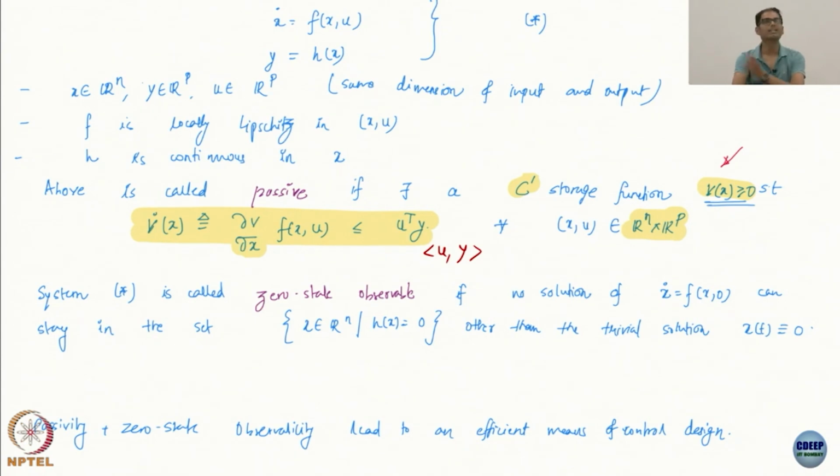So basically the way all these definitions are stated, observability, controllability, it says that you can reconstruct the state from the observations. This is the thing, can you reconstruct the state from the observations or not? That's the whole idea. You try to formalize it in many different ways, but the basic idea is to reconstruct the state from observation. And what do you mean by reconstructing states? For most systems governed by ODEs, all you need is the initial condition, right? Once I give you the initial condition, the entire state is reconstructed.